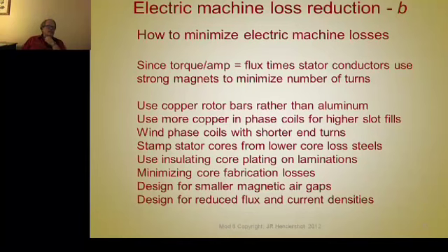But for 4-pole motors and 2-pole motors, the yoke is far more mass than the teeth. And remember, losses are in watts per pound or watts per kilogram. So by running the flux density up a bit high on the teeth, you improve your current density, but you don't affect your flux density penalty on core losses that much.